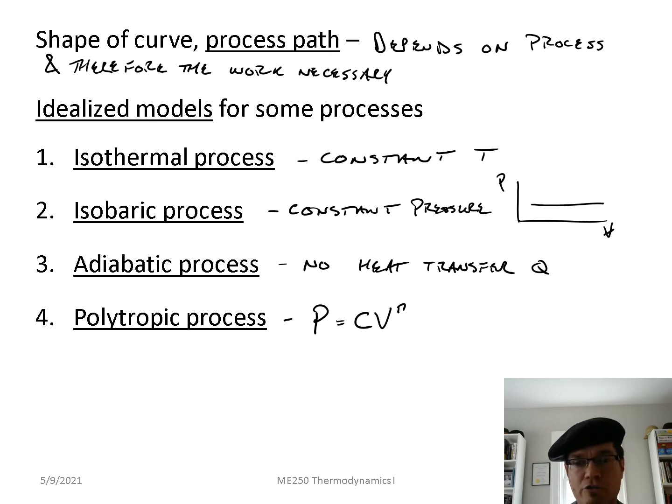But just picture in your mind for a moment that certainly the pressure versus volume that you'd have in that syringe would change depending upon how you compressed it and what else you did to it. If you were adding heat to it or removing heat from it or preventing heat from flowing. And also think about the fact that as a result, it might be really easy to compress that syringe or really hard to compress that syringe. So the amount of work depends upon the process, which is why work is called a process variable. So we'll leave it there for now, and come on back and do some more about energy and conservation of energy in the next lecture.